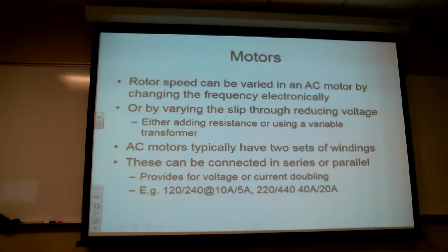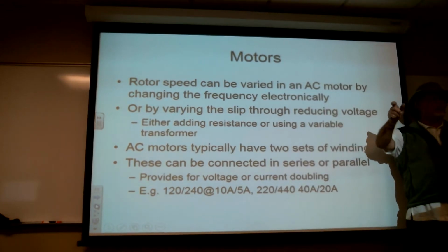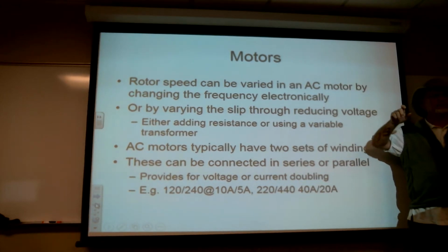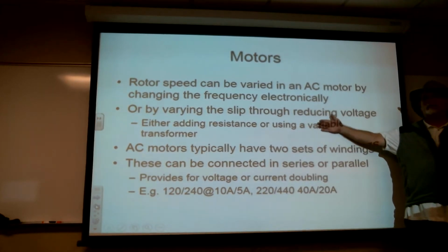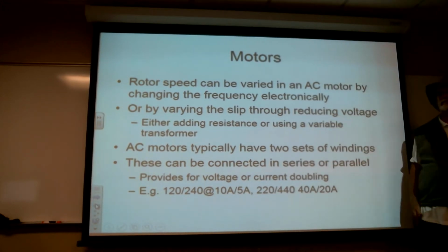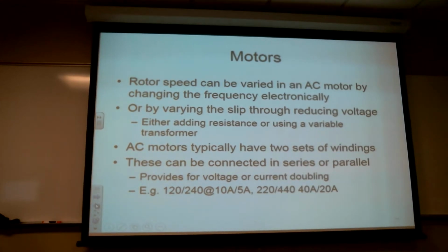More often, and this is why with a DC motor, if I put a big resistor in there and just turn the resistor up or down, I'm going to change the speed, right? Here, putting a resistor on there and an unloaded motor in particular wouldn't change the speed at all. It would strictly be a function of number of poles, time, number of poles, and the frequency. Okay.